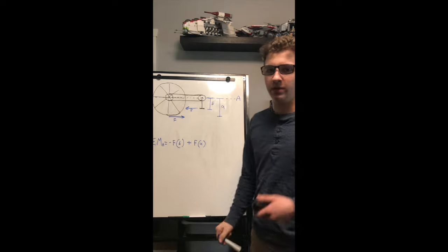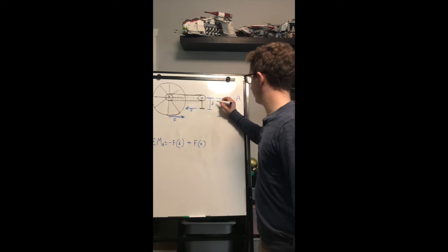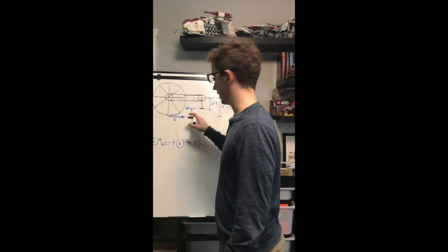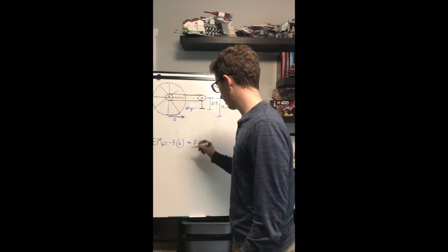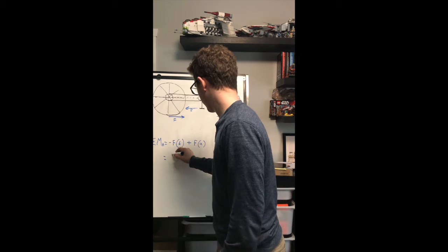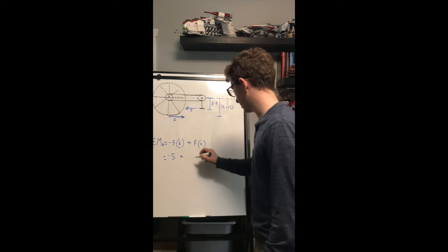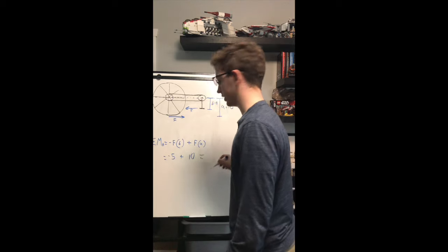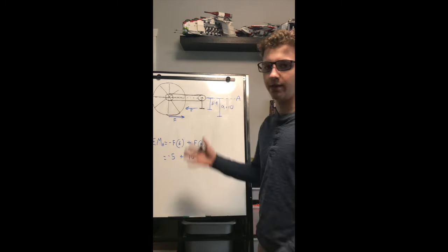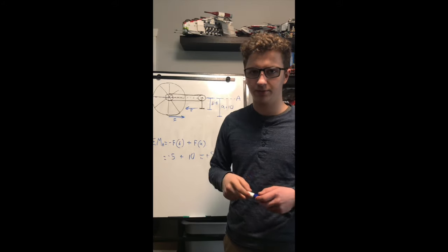In that case, we see the same situation with the wheel. If we assume that B is 5 and A is 10, and let's say the force is 1 Newton, this is going to equal 1 times 5, negative 5, and 1 times positive 10, plus 10, resulting in a net torque of plus 5. That's going to rotate the system backwards, as we saw in the spool demonstration.